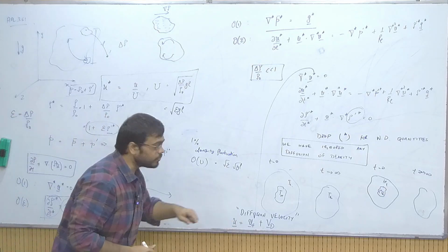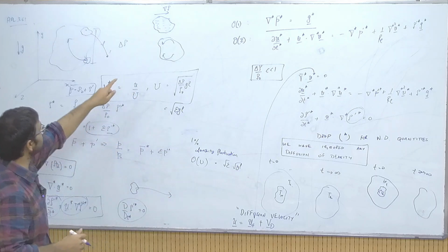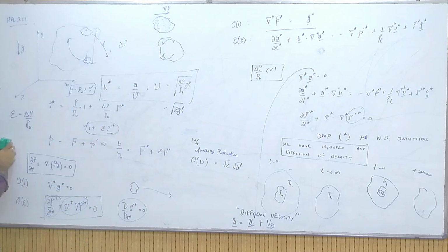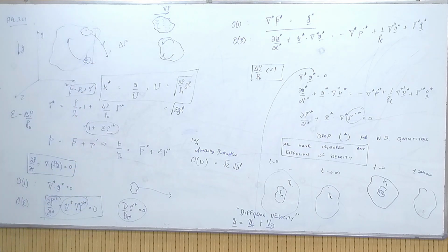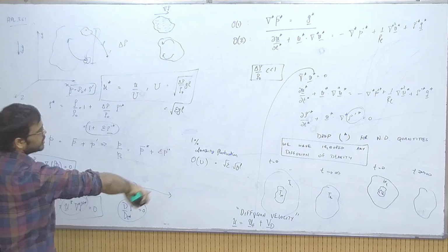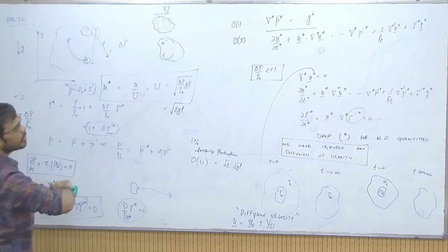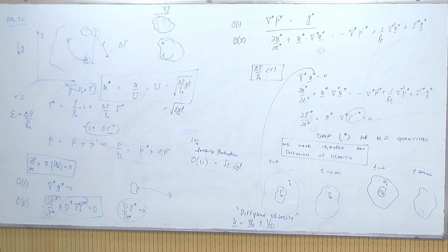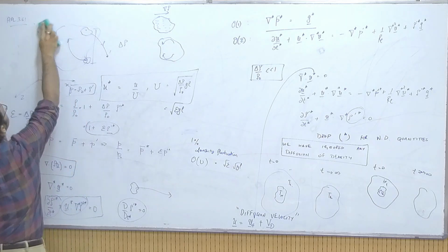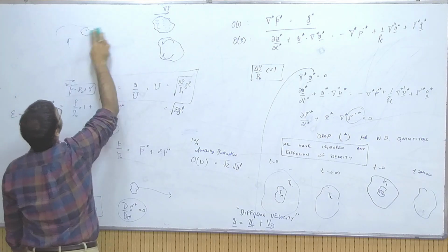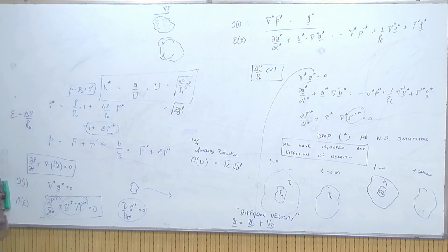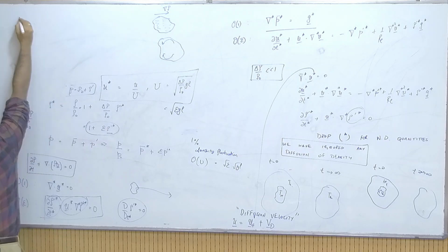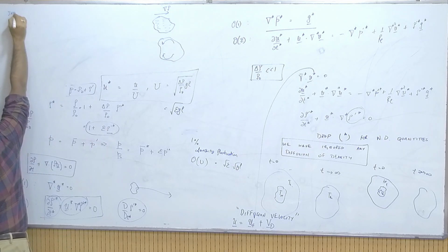Now this diffusion velocity is important when we consider a very standard case of the Boussinesq approximation, where this density change is happening due to temperature changes. All of this analysis holds, but we have to also account for the temperature equation. So if we account for the temperature changes, then we have to consider the internal energy equation.